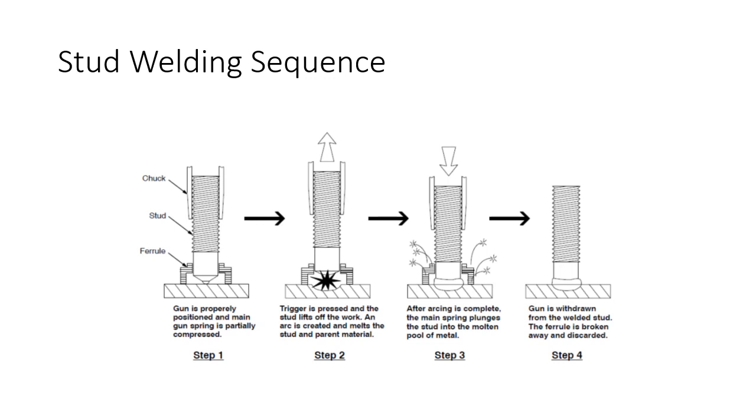I think the automotive industry uses a lot of them for clips, little different kinds of clips. I used to work for a hydraulic cylinder outfit that would put the ports on the sides of hydraulic cylinders. They'd stud weld them on, and then they'd come in later with a drill and drill through the port, but it was already threaded, so it was just 90 degrees. So they could just crank these out as opposed to hand welding them.